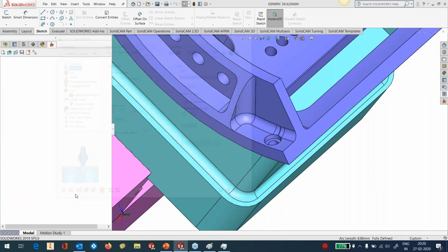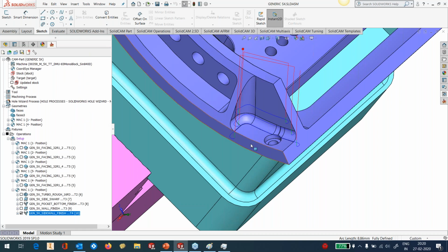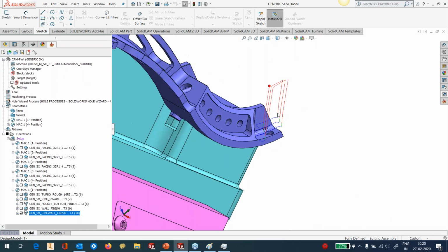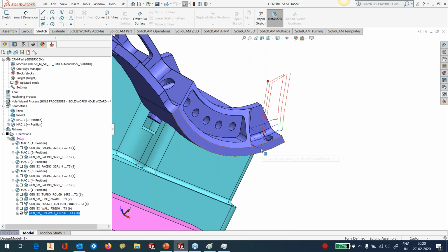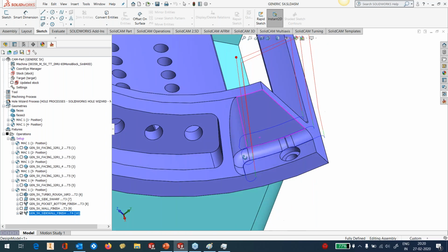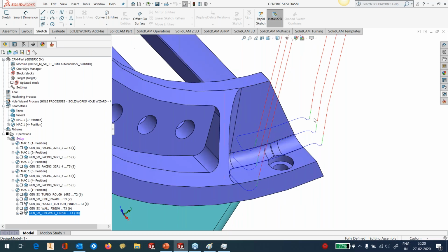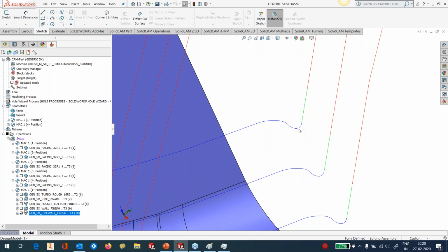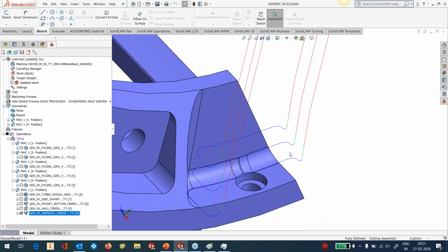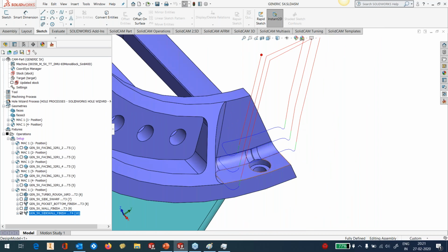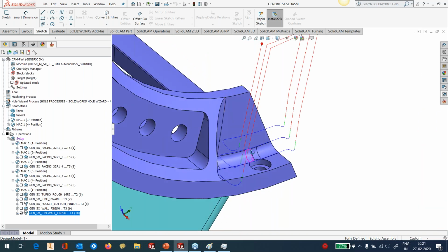That's the best part of templates. You just pick the geometry and your calculation is done. Again, automatic clearance plane. No need to define anything. Okay, you can see that. And the most important thing I missed, automatic arc. It uses dual arcs, horizontal and a vertical, and applies it according to the situation and according to the geometry. Okay, so 3 passes and my wall is done. Simple.